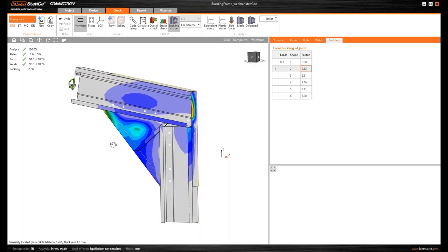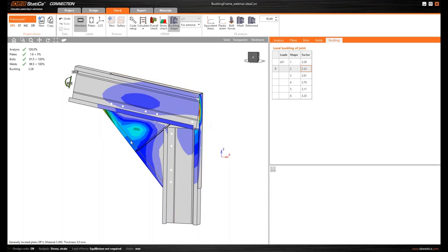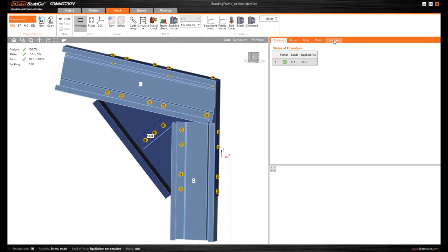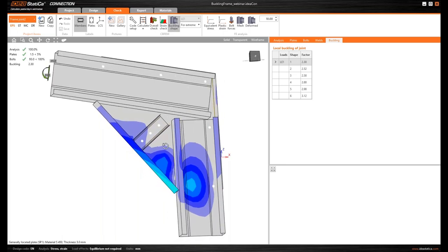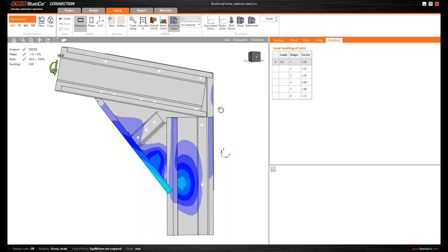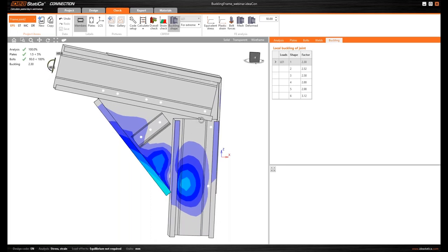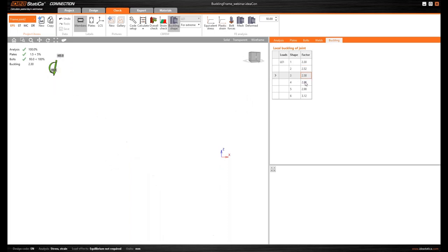And because it's a bolted joint, and this plate will probably be bent, I don't really want to have a welded plate here, so I can add a stiffener in a different way, for example this channel profile, and I can bolt it together, which gives me a better way to build it, and I can evaluate again the buckling factors.